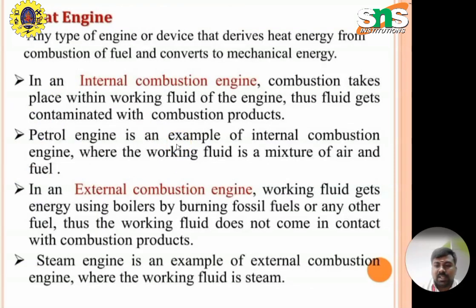Before the diesel engine, we should know what a heat engine is. It is any type of engine or device that derives heat energy from combustion of fuel and converts it to mechanical energy. In an internal combustion engine, the combustion takes place within the working fluid of the engine. Thus, the fluid gets contaminated with the combustion products. Basically, heat engines are classified into two types: internal combustion engine and external combustion engine. Internal combustion engine means the combustion takes place inside the cylinder.